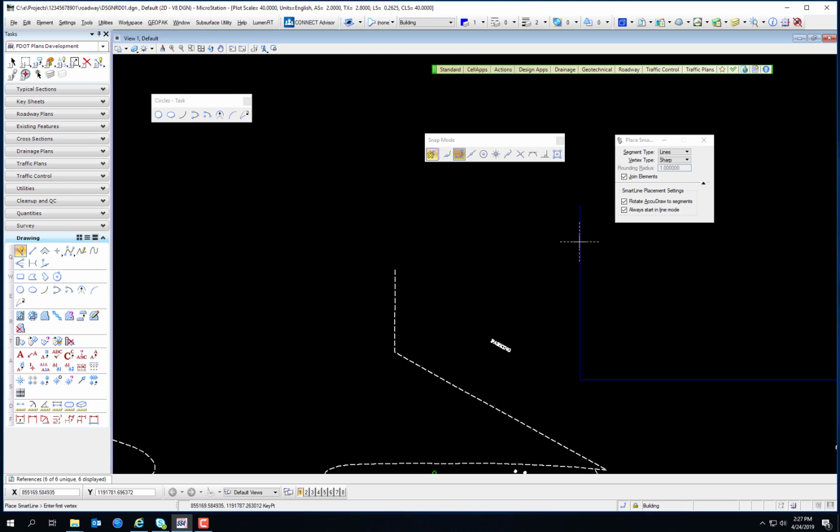See, I can't snap in on anything that's not a key point. It just gives me a little dashed plus sign there. But if I get close enough to a key point, it jumps to that key point and says, ah, you're trying to snap to that. And then to execute the tool, then I enter a data point, and it accepts the snap. So there's AccuSnap, which provides you an interactive tentative, and then there's the actual tentative where you hold down the 2-button chord and you get a tentative snap. And if you want to get out of the tentative snap, you can just right-click to reset.